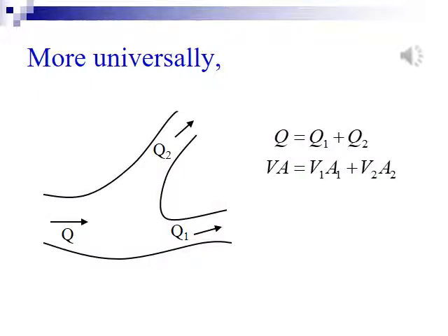When we meet branch flow, again, what comes in equals what goes out. Of course, this is for volume per unit time, or flow rate. Really, for homogeneous fluid, it represents mass per unit time, because density is constant everywhere. Now pay attention. The continuity equation is just a scalar equation, nothing to do with directions.